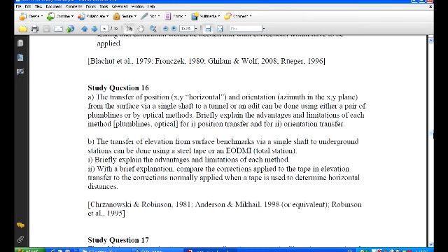The concerns with it would be that you then have to account for the fact that you're using the steel band that's very long and take into account all the different corrections that would have to be applied. And it gets a little more complicated with temperature because of the differences in temperatures. You go down the shaft and there is a formula for calculating the weighted average temperature, which is then used for the calculation of the correction.